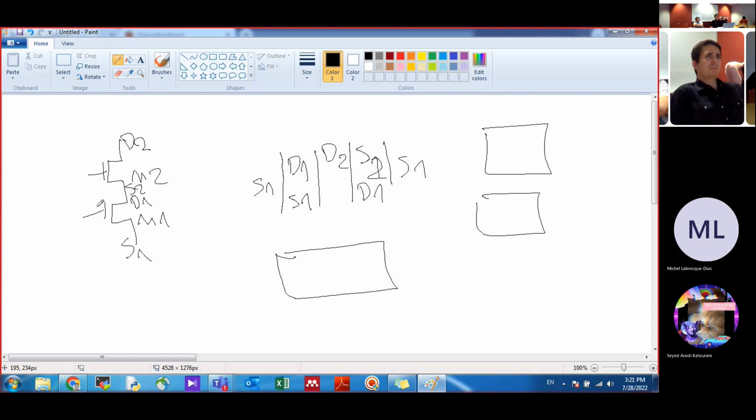I always wonder when I'm wiring, if passing in front of gates is a bad idea. Like you have your metal two, and you pass your metal over the gate. I always wonder if it is a really bad idea to do so because you make some capacitance. Yeah, I think it depends on the design. Maybe in high frequency.